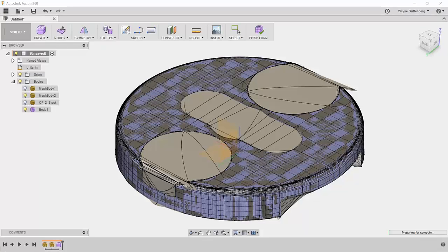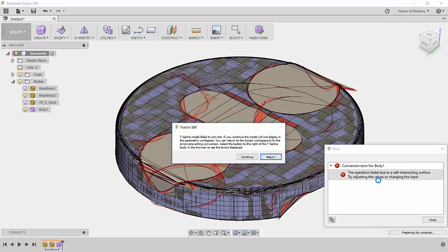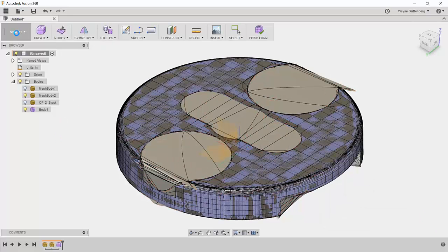And I might just add, even on a part like this, another way that you could use it, sometimes people completely forget about, but oftentimes you'll just use the mesh as a canvas to model over top of. So you'll look at that outside thing and maybe you put some calipers on it and know that the outside is a circle that's exactly 3 inches. Some of the other features you've got less certainty over, and you just model your parametric model close to it, but you can certainly use the mesh as a canvas and then create a true solid around it. So I wouldn't go and forget that.